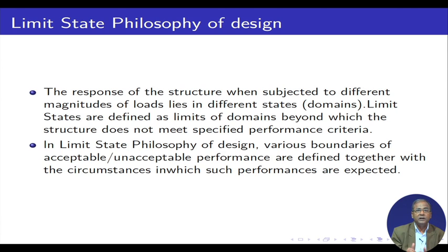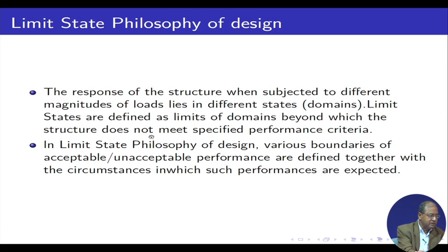We give different boundaries, and that is why we call it partial safety. We are giving different boundaries and working within that particular domain. So, you can consider we are giving a boundary for steel, for concrete, for loading, for deflection, like that we give different boundaries. It is not only one unique criterion that only gives stresses.